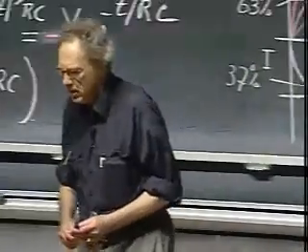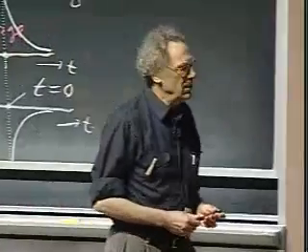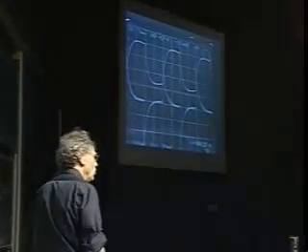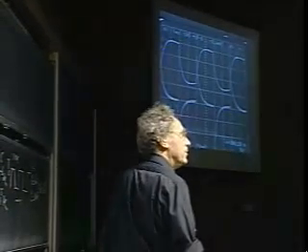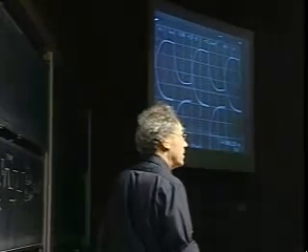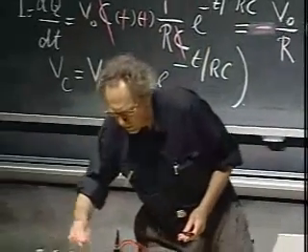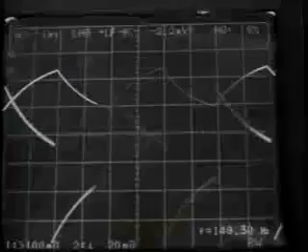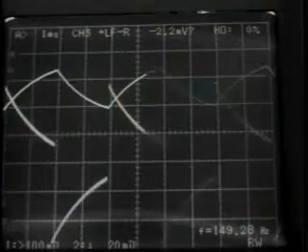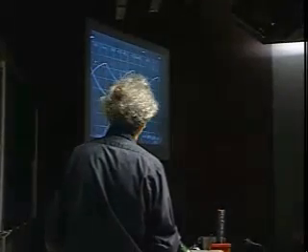What I can do now is to increase my capacitance by, for instance, a factor of 5. So that would change my RC time to 3 milliseconds. So now there is no way that the capacitor can become fully charged in the 4 milliseconds that it has. And you will see that indeed if I make this 0.5 microfarad, then you see that the capacitor has not enough time to get fully charged.